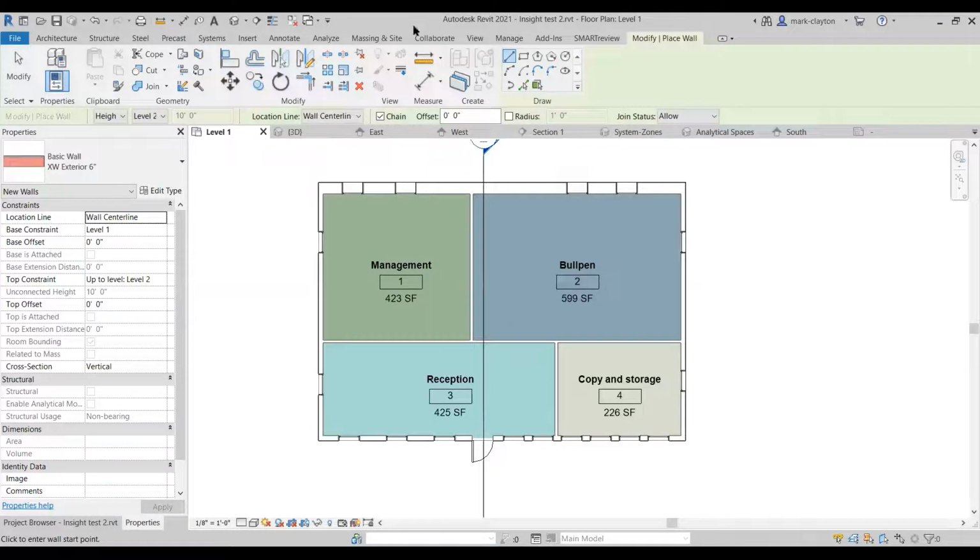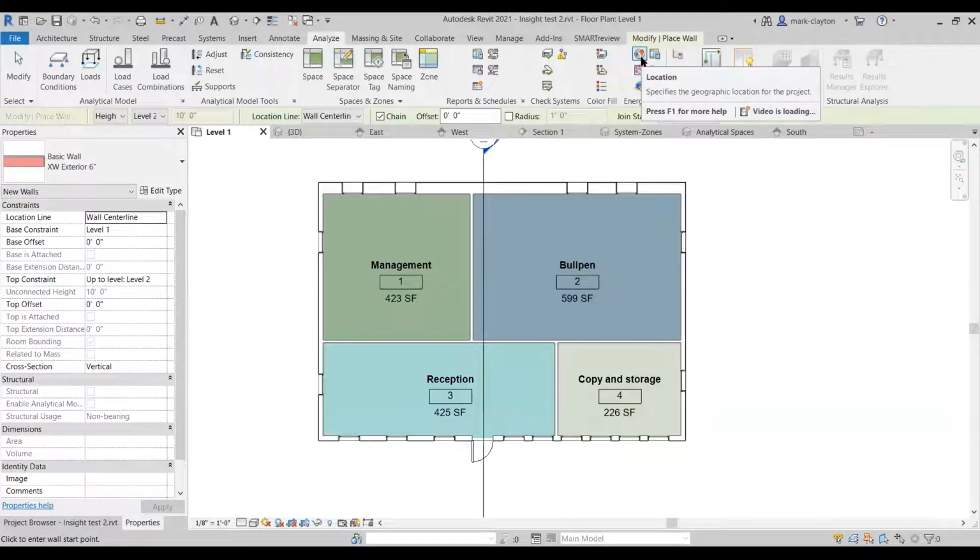So managing those U values in construction. The next assignment 3 is going to be about construction, so we're going to get into that in detail at that point. And emphasize that right now, because of the way Insight works, it's going to do the calculations for low R value, for medium R value, for high R value.